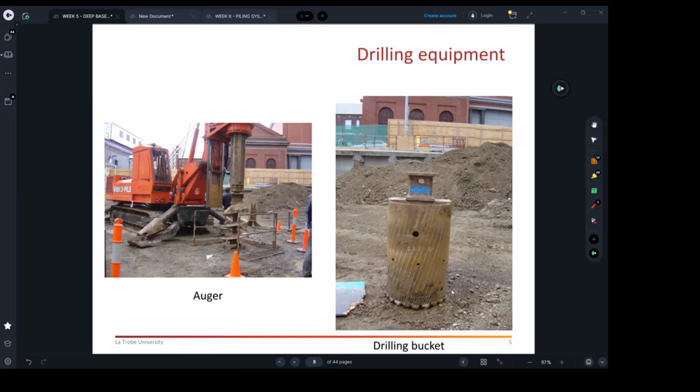And the next day when it's rainy, it's going to be filled back, even for residential. You're just going to need to redo it, because you're going to disturb the whole ground. Usually you need to be careful with time. What I'm trying to say is we assume the hole is going to be self-supporting for a few days until you place the steel if required and pour the concrete.